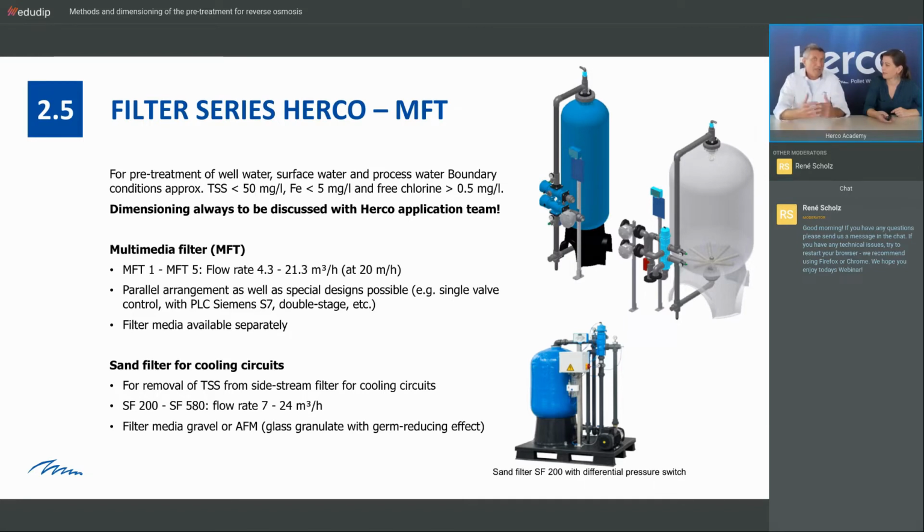Right. And that's why these sand filters for cooling circuits are very interesting for our clients. You can have different filter media there, gravel or an AFM, glass granulate, and this has a special function of germ reducing in these cooling towers, because cooling towers always have a problem and struggle with biological impacts. Biofilm, all that. Biofilms, exactly. Okay. All right.